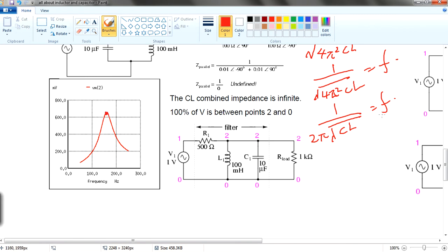When the inductor and the capacitor share the same frequency, they actually have an infinite impedance, which is very high, over here. So if your frequency is lower, as you know this is the frequency axis, it's not necessary that the frequency must be very high to reach that top value. It's just when the capacitor and the inductor reach the same frequency, they will spike. This is the beauty of it.